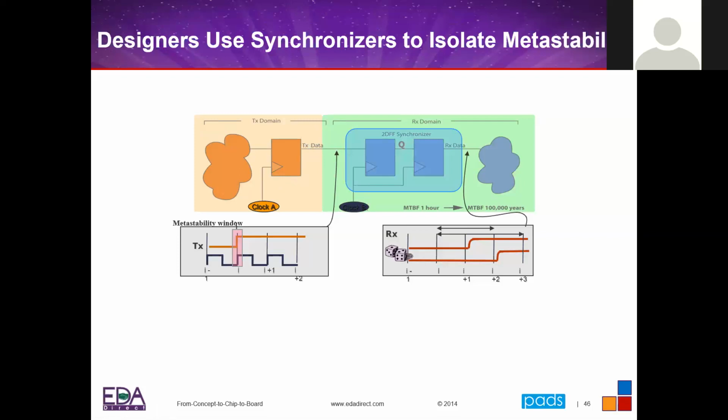So basically what that means is the data rate on TX data has to be less than or equal to the clock rate right here, so that I guarantee that I'll catch any changes on that data. So even this simple thing, I have some timing issues that I have to meet.